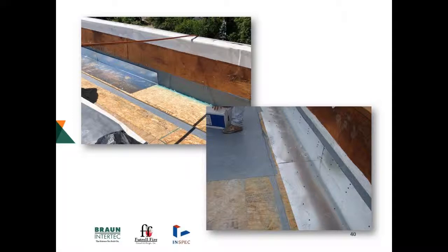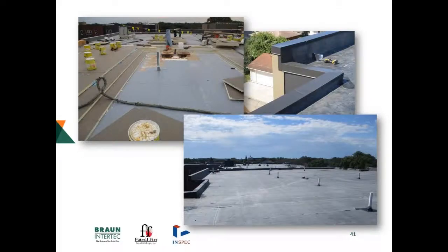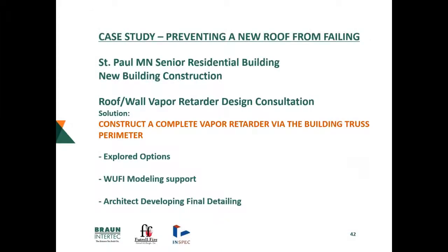So now we have a continuous vapor retarder on the roof below and connecting to the Z, down the foam to the wall itself, vapor retarder, doing the successful job of connecting all that. Then it became a relatively straightforward re-roofing project. You know, multiple layers of insulation and low-rise foam, staggered, slope to drain, 60 mil EPDM membrane, fully adhered, and then our metal flashings.